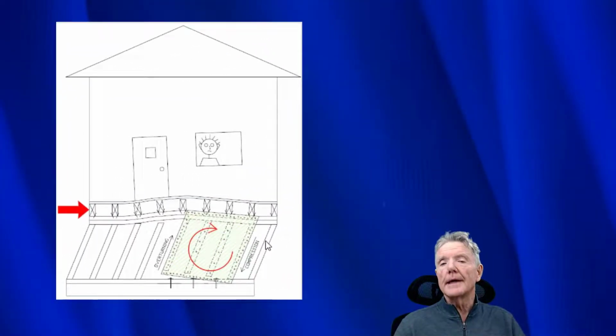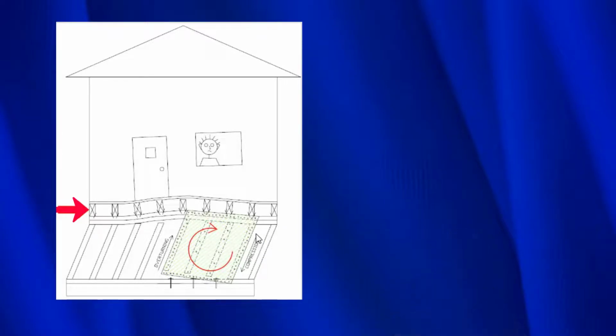Even though we've put in plywood, shear transfer ties or floor connectors, and the bolts, there's something else that can cause our shear wall to be damaged. When you see the earthquake forces coming in from the left here, the shear wall is going to want to overturn, and this is it. It's trying to flip over like that. Very understandable that that would happen.